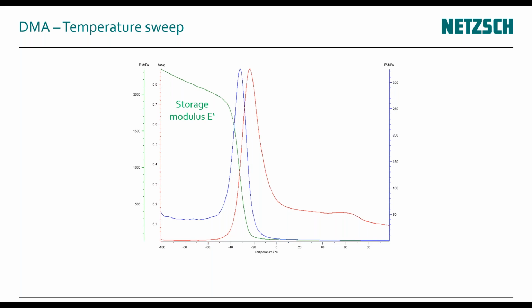And that, so I say this refers to the stiffness, so we are actually losing the stiffness of our material at this point. The second parameter, the loss modulus, displays a large peak here, displayed in blue, at around the same temperature. And the loss factor just comes shifted a little bit later, that also displays a peak.